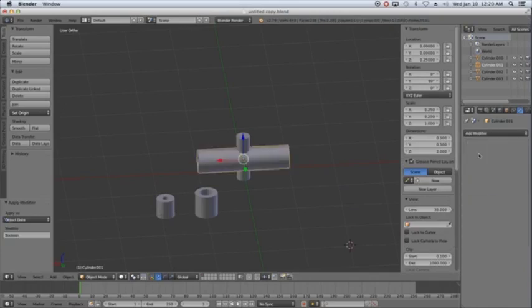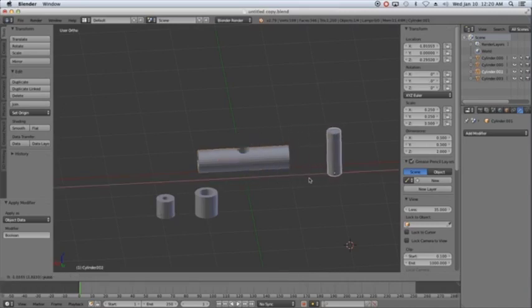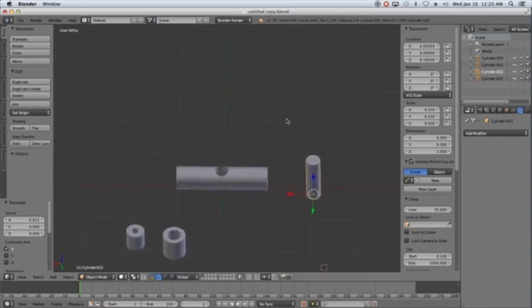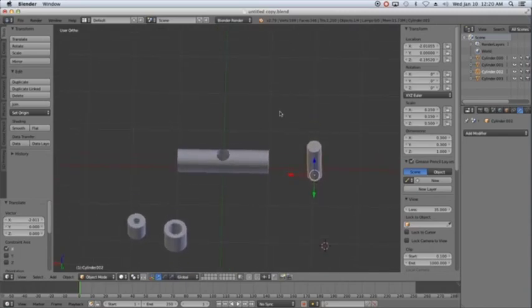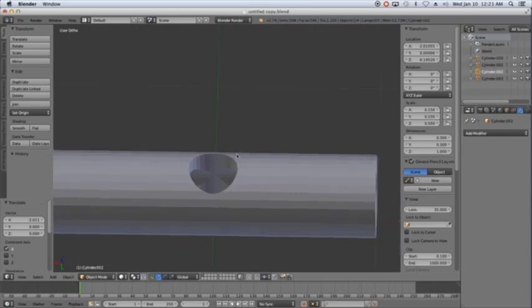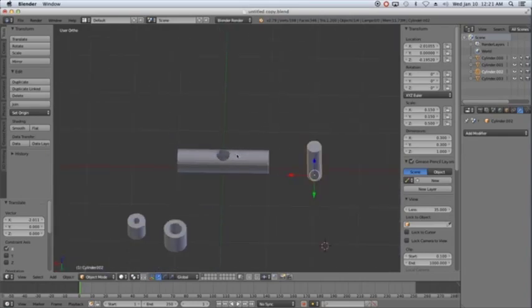I'm going to move this out of the way now, and I'm going to double check. Anytime you poke one of these holes when you have a complicated piece, double check that it actually made the faces here on the inside. Sometimes it'll just do the surface if you have too complicated a figure with things that overlap, but that seems okay. All right, so now I've got my piece that's going to go in the center,